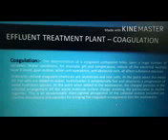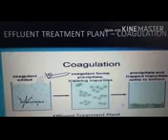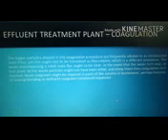This is an extremely simplified view. The colloidal science involved clarifies the turbulence requirements for bringing the coagulant solution into the wastewater. In coagulation, the coagulant forms a precipitate trapping impurities, and the precipitate with trapped impurities settles down to the bottom. This is the coagulation part of an ETP, effluent treatment plant.